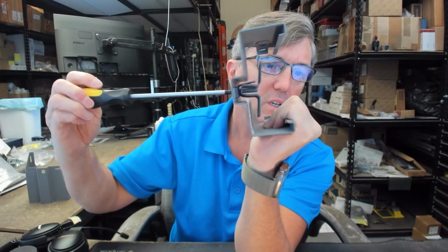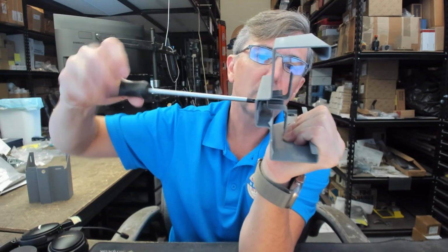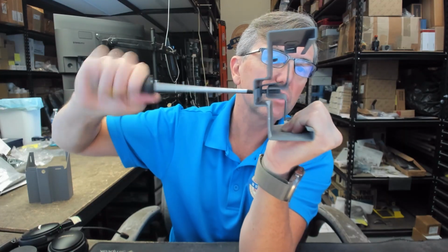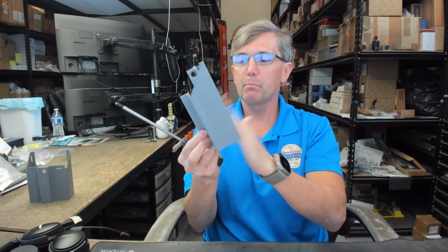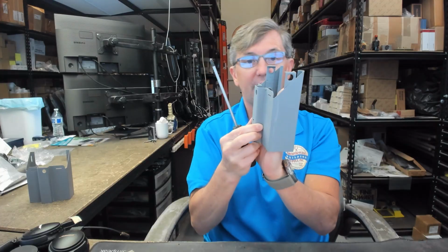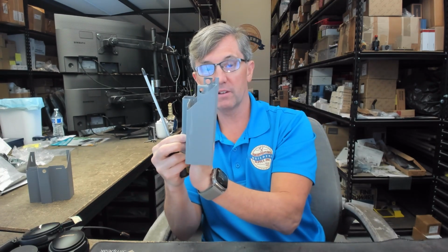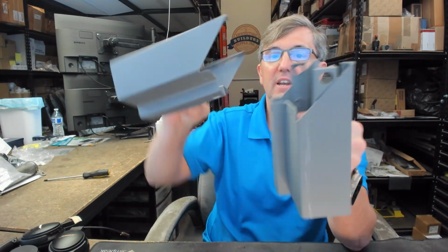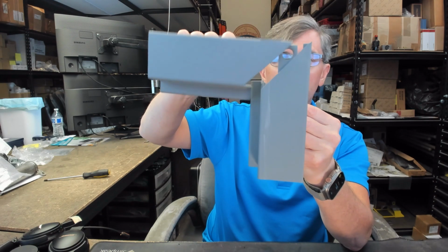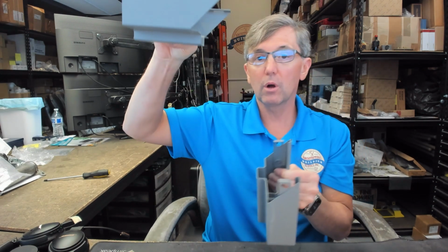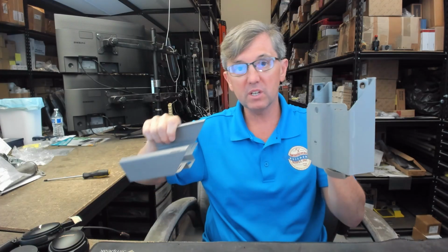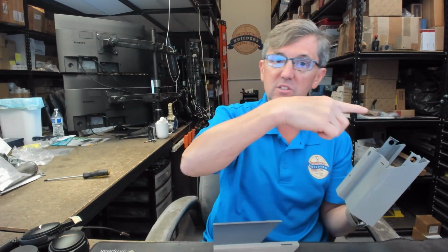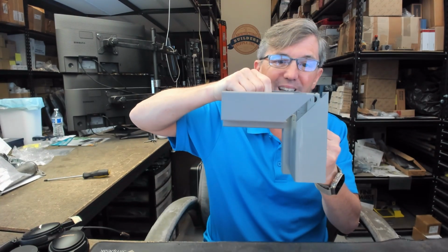And this is part and parcel to how you install a drywall frame. I'm turning it clockwise now. The compression anchor hits the stud, and that forces the frame to move out this way. When you do that, and these two frames aren't meant to go together because they're not notched, it forces that miter to tighten up. The header goes up, the jam comes in, and as you move that compression anchor against the stud, the frame has nowhere to go but that way, and it locks and tightens up that miter.